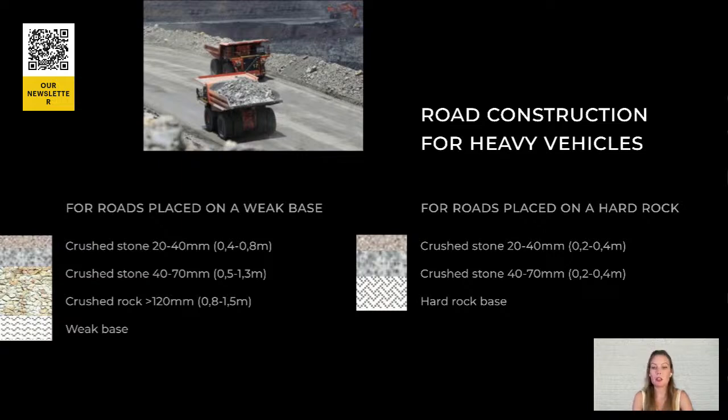For the best results, the top and final layer can be made from finely dispersed granite screenings cemented with special liquid solutions. This mixture fills all the voids and straightens the road surface. Maintaining these roads in good condition is also essential, using specialized equipment like graders, bulldozers, and loaders.